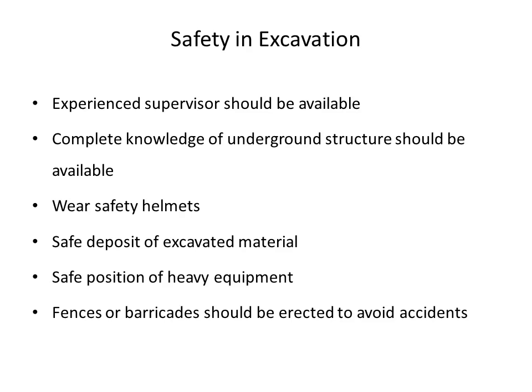Then the excavated material. The excavated material should be kept away from the edge of the trench. Otherwise, there is a chance of the excavated material falling over the worker and resulting in accidents. So we should ensure that there is proper lead between the trench and the deposited material.